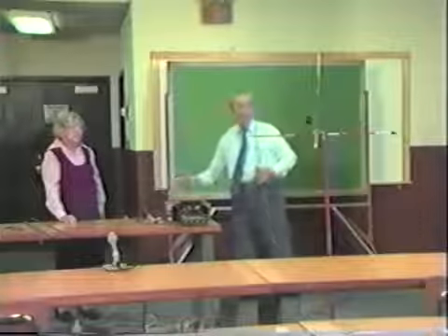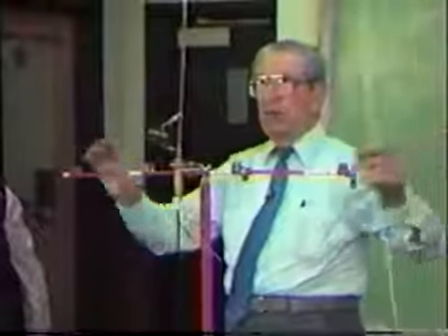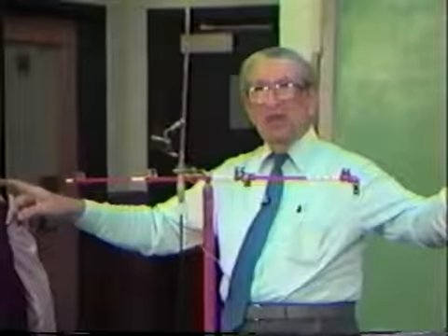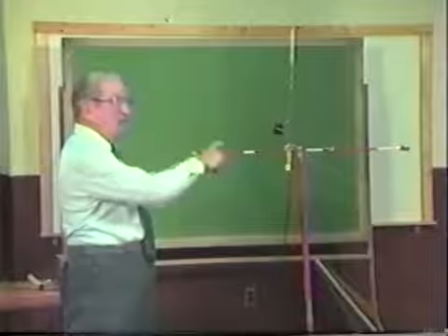If you remember before, when we had the dipole antenna, we had a bar of aluminum, and each side was 18 or 19 inches long, quarter wave, so that the total length of the antenna was 38 inches in the resonant length. Well, now we have a strange phenomena. We actually have here a bent dipole. Here's your vertical, and here's your other part of the dipole.